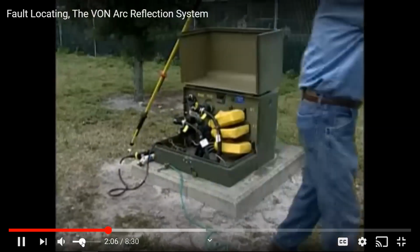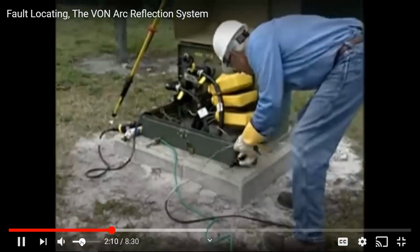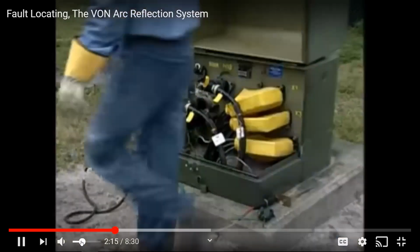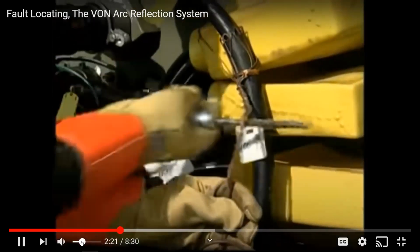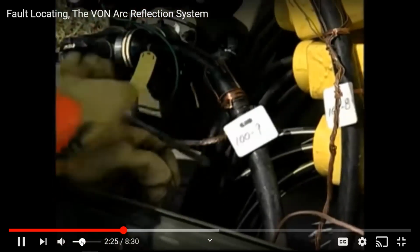Begin by cleaning enough of the neutral bundle so two connections can be made: the green safety case ground Vaughn provides and the approved grounding jumper device that your company uses. Cleaning the connections is the most important step of the hookup process. Notice the lineman cleans the grounds and the concentric neutral of the cable under test.